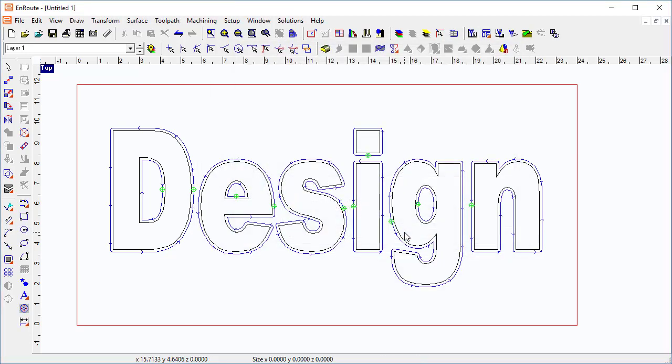So it creates the output, puts it in the folder that I want, and so now basically what has happened is EnRoute has created the PCD, or the P code file, which is the file that it creates every time. It has then activated the PT, which then utilized that driver to translate the code into the appropriate, in this case, G code for the output.